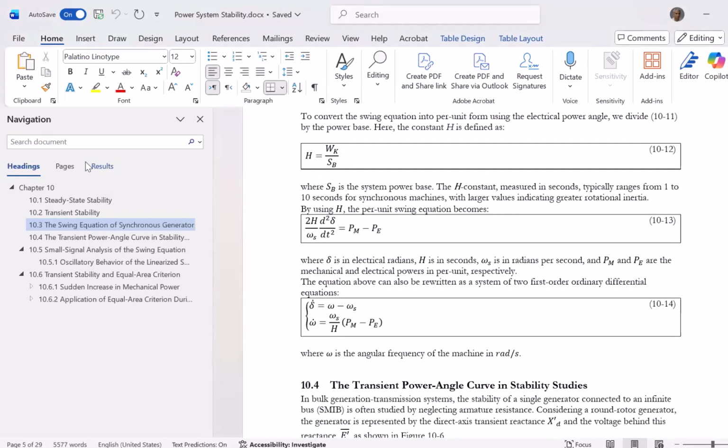In these equations, there is also an H coefficient, which is proportional to the inertia of the rotor of the generator. Its unit is seconds. Roughly speaking, if H is, for example, 10 seconds, it takes 10 seconds for that generator to deplete all of the energy in its mass. So in theory, if H is bigger, that is a sign that we have a more giant generator, a bigger rotor that is very hard to get kicked.